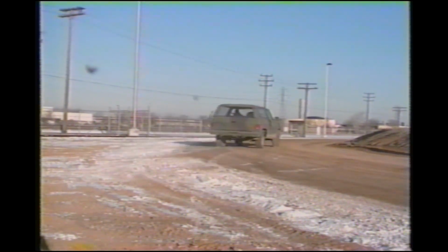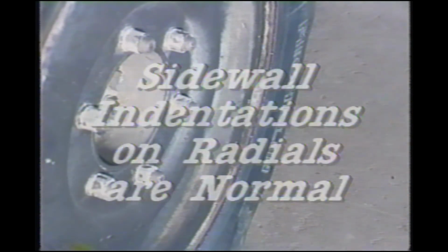A tire that has scratches in or pieces torn from the tread indicates excessive spinning. Tire failure can also be caused by a cut, tear, or puncture. Body ply separations can be detected by a lump or bulge in the sidewall. Radial tires have slight low spots or a wavy appearance in their sidewalls. This is normal. This is a tire that has signs of weather cracking or ozone damage.